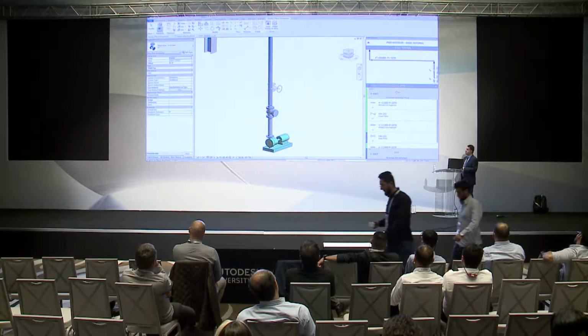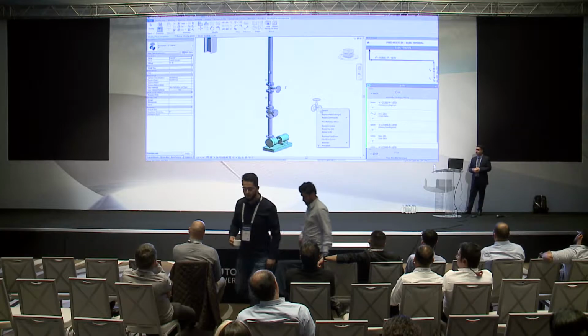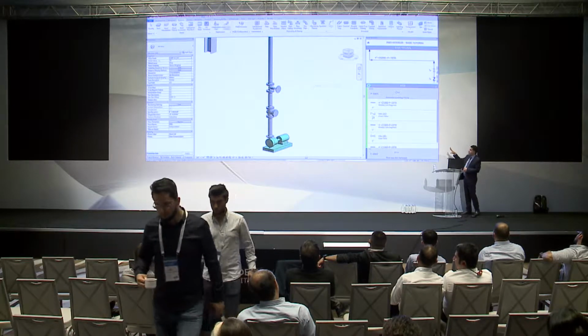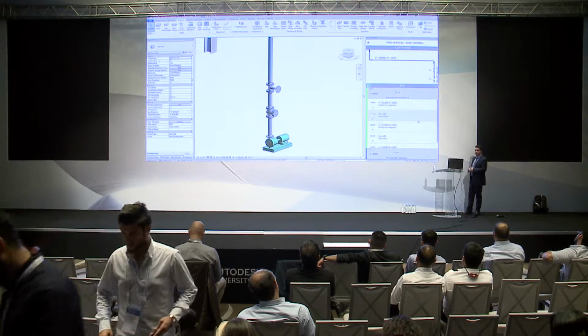It will highlight that this has been placed wrongly on a particular side. And once everything looks fine, once all those maps have been done between the schematic or P&ID as well as the Revit elements, you will see that this progress is green. On top, there's a green dot, meaning this service of the line has been completed successfully without any error